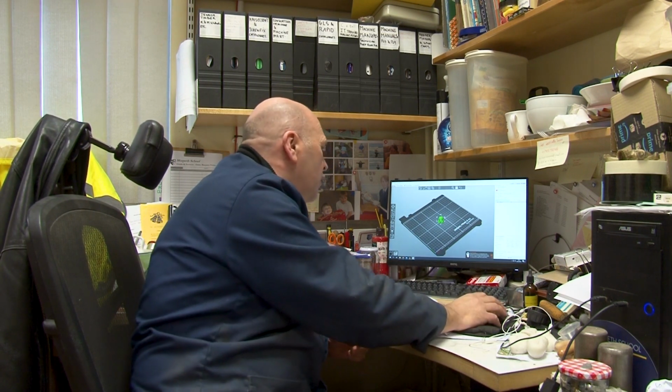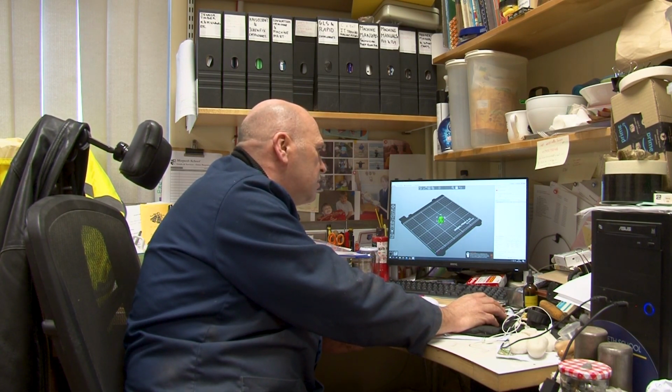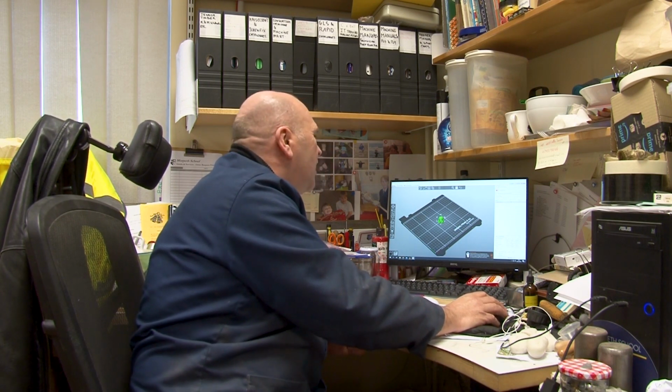There are some things you could probably make, like that dice, that doesn't really need an infill, to be quite honest with you. And when you get a bit more advanced, you can do an extra wall thickness and make that wall a little bit more robust, and then you don't need an infill at all. So it will print even faster. So when you get a bit knowledgeable, I think is probably the best way to put it, you can get more proficient. I'm trying to find the words.